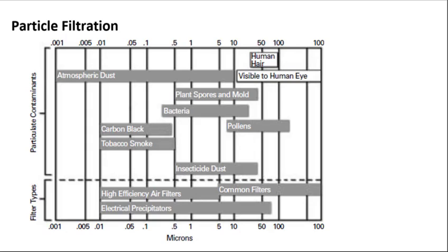For particle infiltration, we see here a chart similar to one shown in an earlier lecture with the size of particles on the horizontal axis and types of particulate on the vertical. Note that the horizontal axis ranges from submicron particles to 100 microns. 10 micrometers and smaller, the size cut for respirable particulate that can penetrate more into the lungs, is around here on the plot.